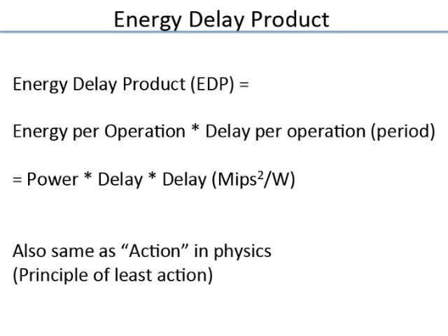So it's not an unfamiliar concept. It has a nice significance, the energy delay product, which you would like to minimize. If you have 2 designs and you want to see which one is better, you look at the energy delay product and you say the one with the lower EDP is a better design than the one with the higher EDP. Of course, you can change the weightings. You can say, look, I really am more interested in delay.